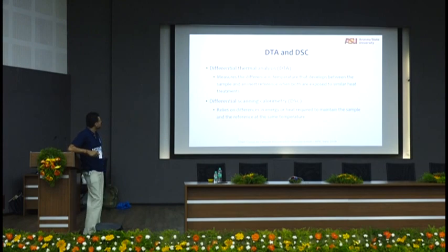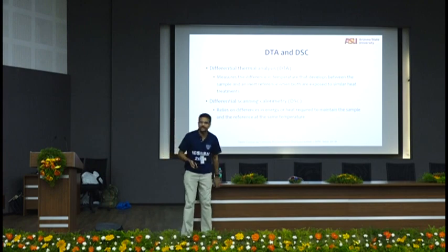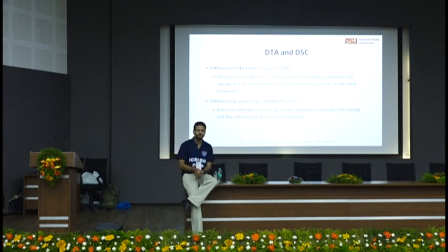You can do differential thermal analysis, which measures the difference in temperature, or differential scanning calorimetry, which relies on the difference in energy. These are a little more advanced techniques, DTA and DSC. Thankfully, this equipment has become less expensive now. It used to be very expensive, but with advances in electronics and instrumentation, these have become less expensive.